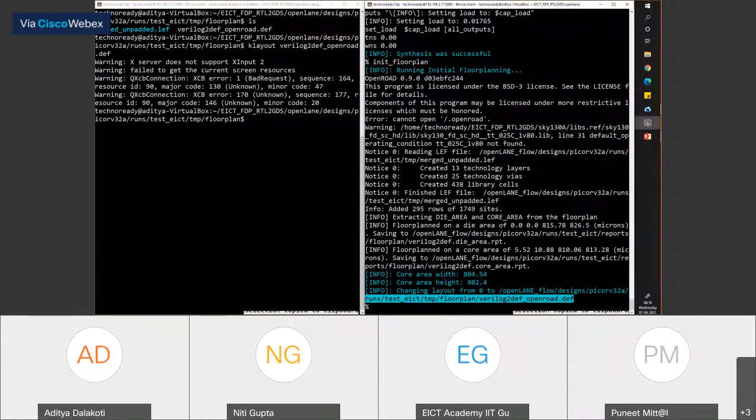The script, what exactly you have to paste has already been shared with you. So change those widths, those heights, those pitches and everything, and try to observe if you are able to see a change in the PDN generation. So do that at your end today. We'll just run the command today and proceed to the further aspects of the design.